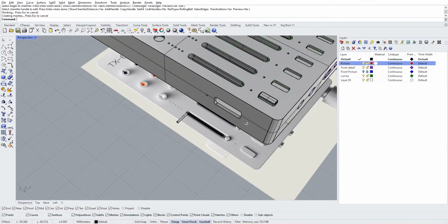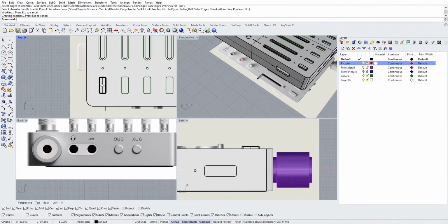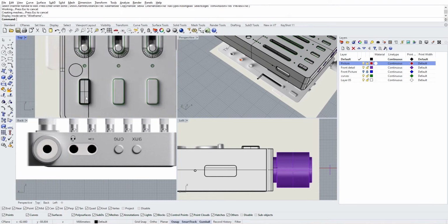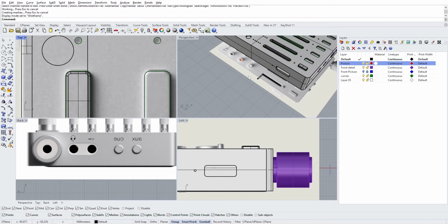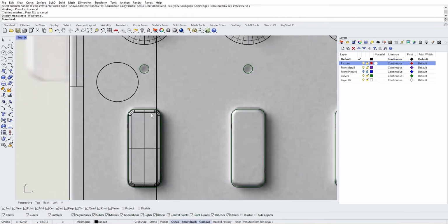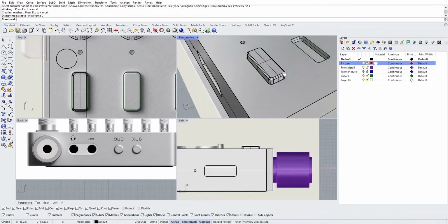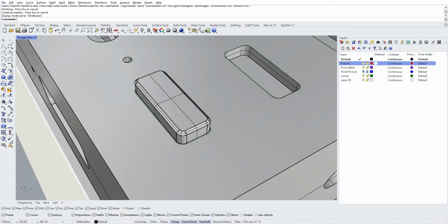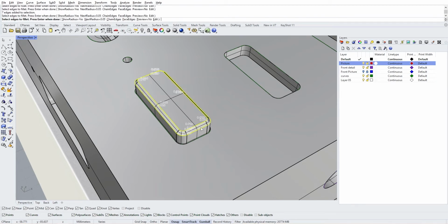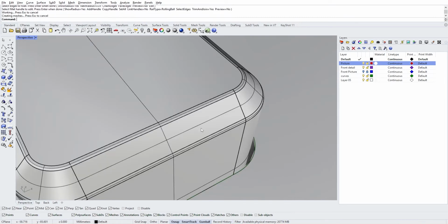I think 0.2 is okay. We can put it into wireframe and actually look where on the picture it stops. And I think 0.2, yeah, is fine. So let's keep it at 0.2. And so that was the 0.2 chamfer, and then there is a little fillet of probably even less, so 0.05, let's say, here and there. Yeah.